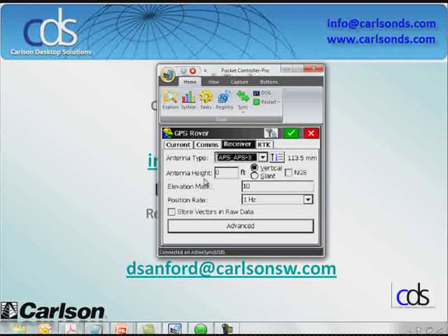Outside of that, probably the best third party I've seen is from a Canadian company called OnPOZ, and the product is called EZSurv. That's a good option if you're not using TGO or LGO, but those vectors or any kind of static processing or post-processing would be done through those products. This is simply how SurvCE stores that inside the raw file. So that's what the store vectors and raw data option does.